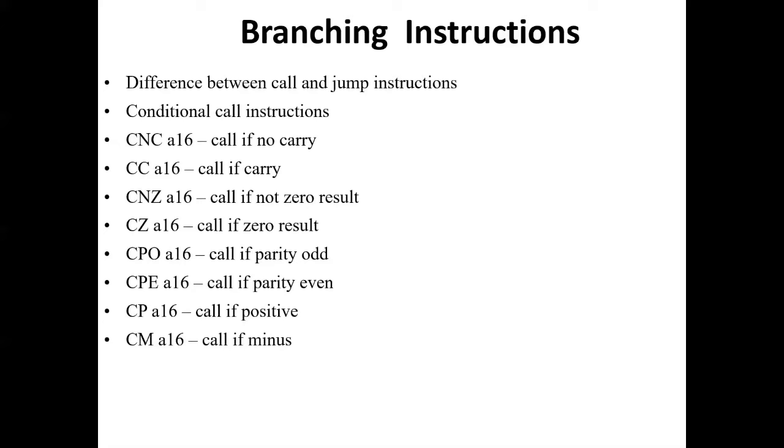And the last one is CM A16. CM is a mnemonic which stands for call if minus. This instruction is used to branch to the subroutine whose 16-bit address is provided in the instruction only if sign flag value is 1. If the sign flag value is 0, program flow continues in the main program sequentially.